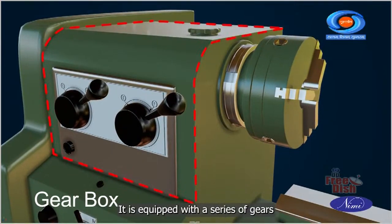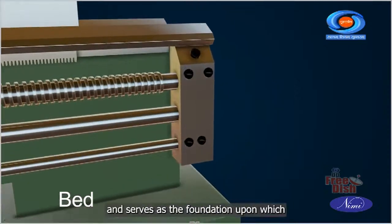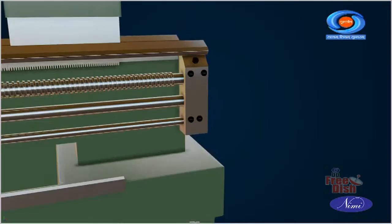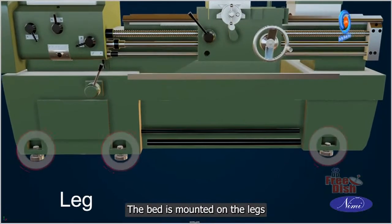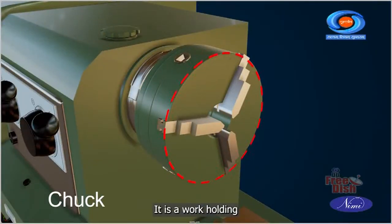Gearbox. It is equipped with a series of gears which provides a range of feeds and threads to the machine. Bed. It is a casted part and serves as the foundation upon which all other components of the lathe are installed. Leg. The bed is mounted on the legs which are bolted to the ground. Chuck. It is a work holding device used to clamp the job.